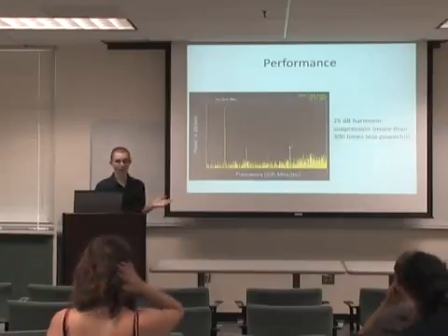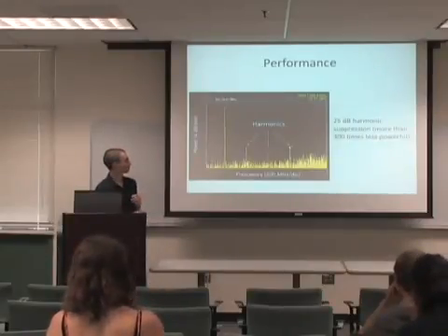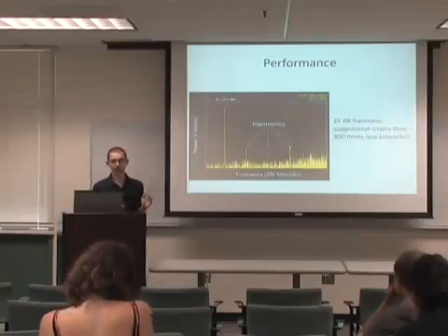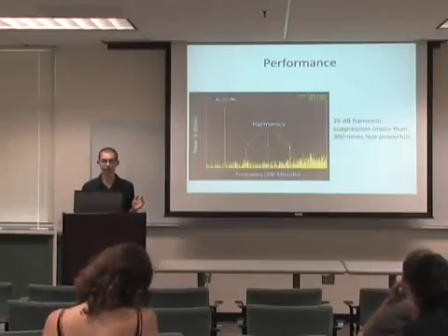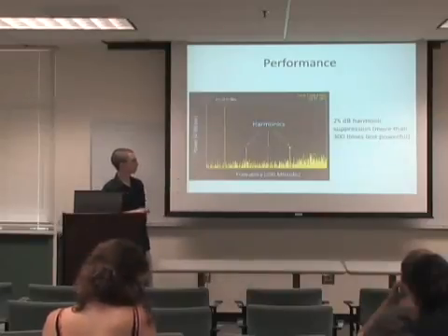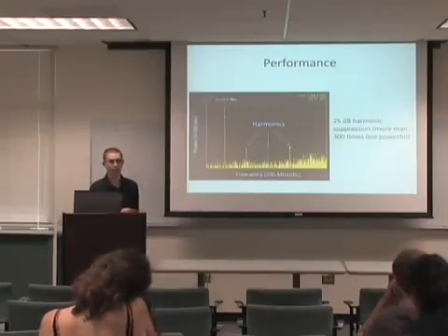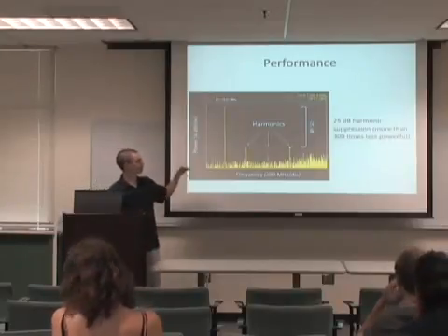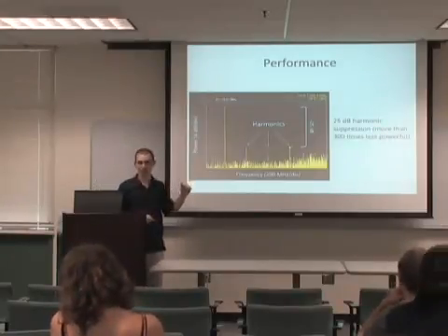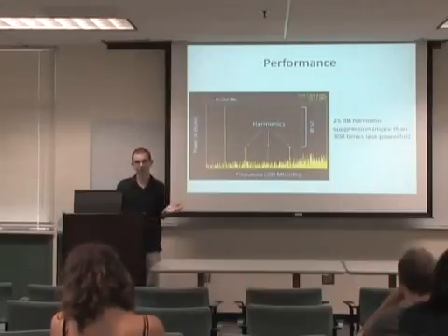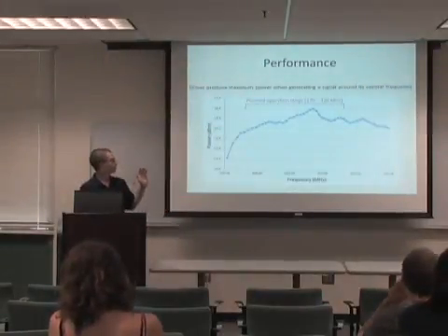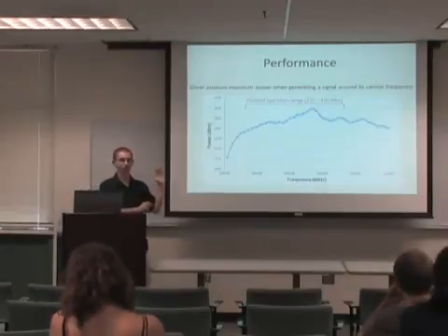A byproduct of these devices is something called harmonics, which can reduce, I guess, the efficiency of the AOM. So we want these to be as small as possible in comparison with the main signal we send out. Looking at the graph, we can tell that their intensity is 25 decibels less than the main signal, which is about 300 times. That's pretty good.